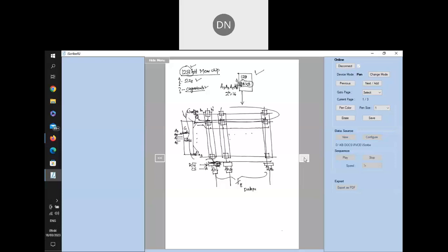So you have to take the encoded address information, what is available in the address lines, decode them, and select one of the rows or one of the words of the memory chip. Once you select one of the words, the contents present in the cells of that word will be read or written using the sense and write circuit with the help of the read/write bar and the CS lines. This is how the memories are organized.